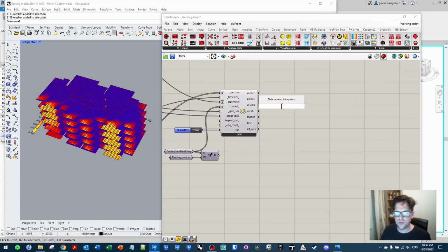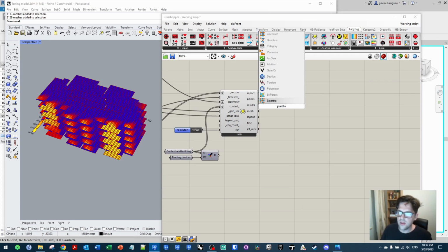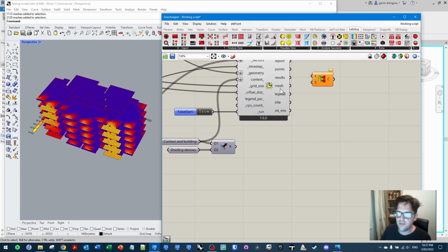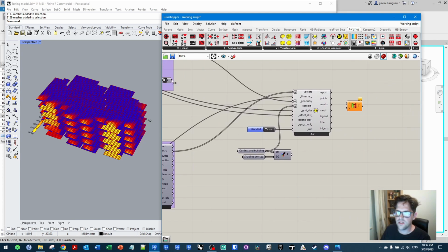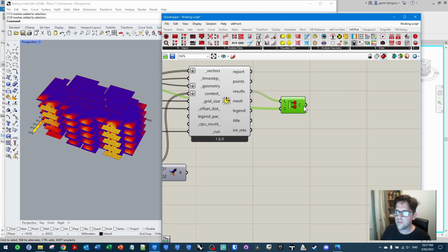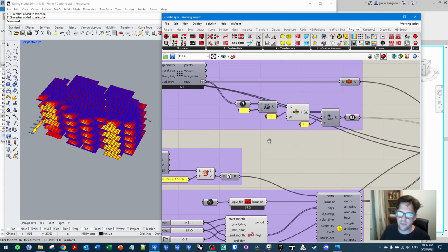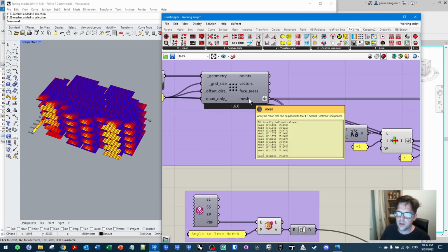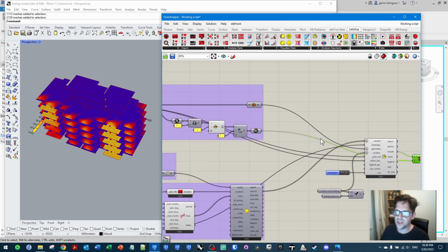So we're now going to break our results into sublists. So we have at the moment just a big list of results, and they're just taken in the order of each mesh face. Now remember, we know how many faces each mesh has, so we can actually use that to partition our result into sublists per apartment. So we can see, for example, the first list here has 348 results. If we go back to our original meshes, I can see in this case that I have a face count of 348. So we can see we've consistently partitioned our results based on the mesh face count.